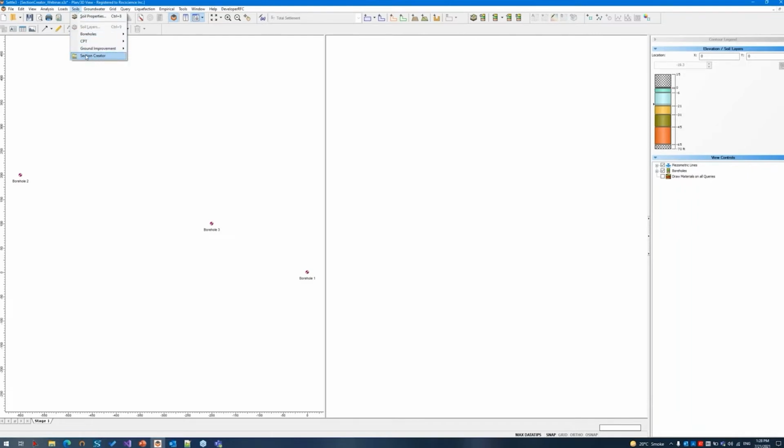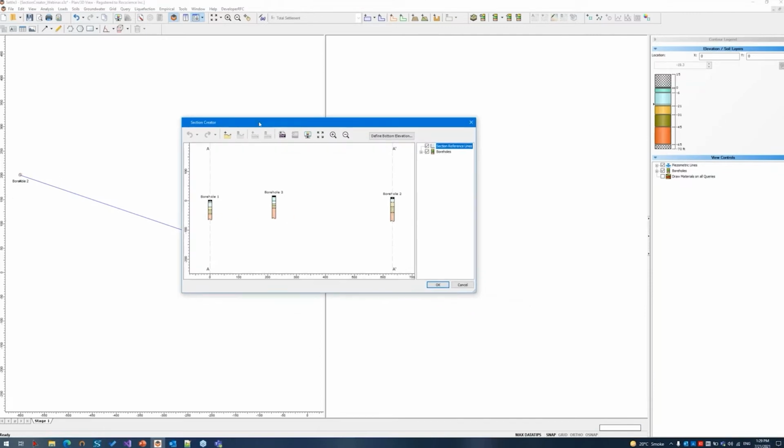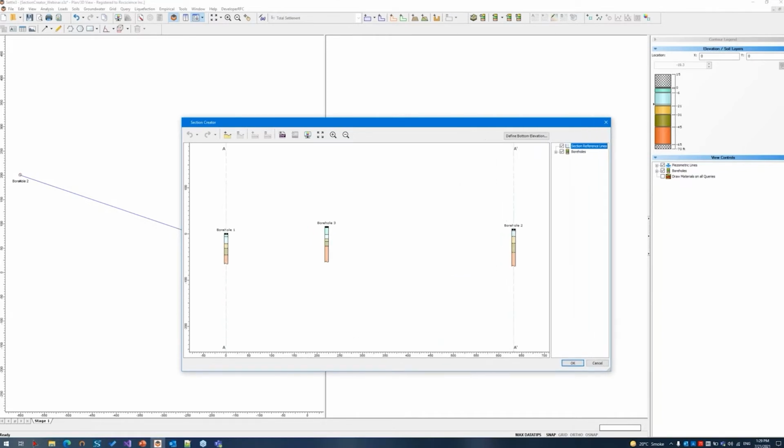And you can see the section creator over here is enabled. Click that. The cursor then in the plan view will become a cross. This is because the first step to create a section is to define the section line. So we have to define a starting point and the end point for this line. And these perpendicular dashed lines are here to help you to visualize the potential extruded area. So once you define the section line, this section creator will pop up for you.